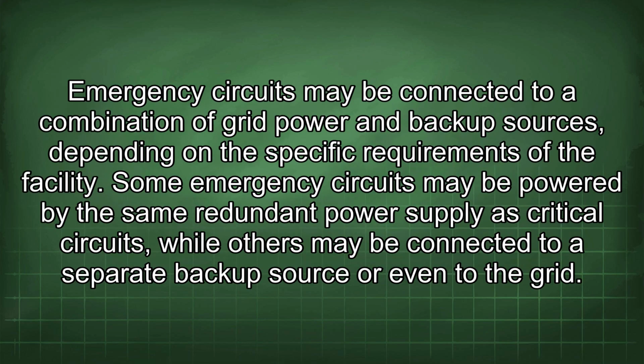Emergency circuits may be connected to a combination of grid power and backup sources, depending on the specific requirements of the facility. Some emergency circuits may be powered by the same redundant power supply as critical circuits, while others may be connected to a separate backup source or even to the grid.